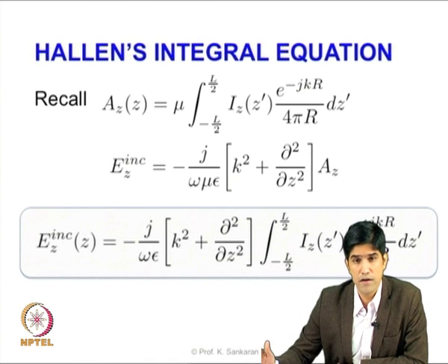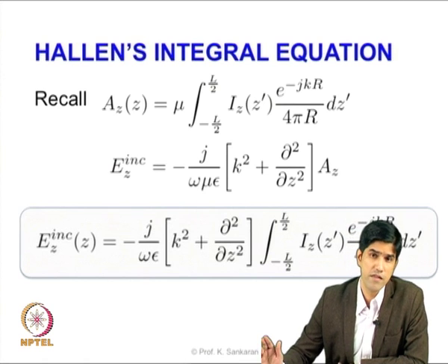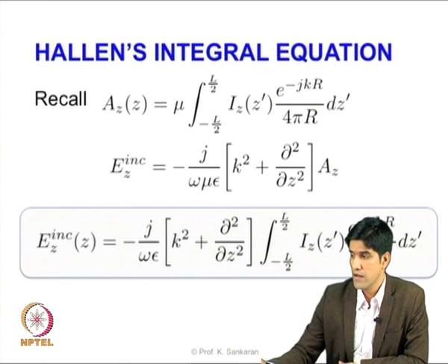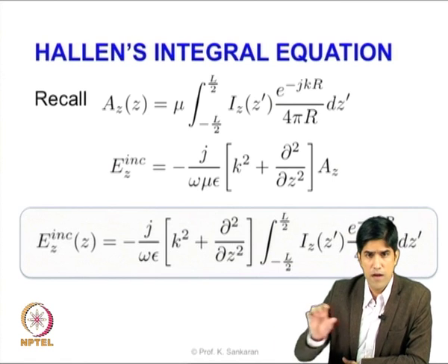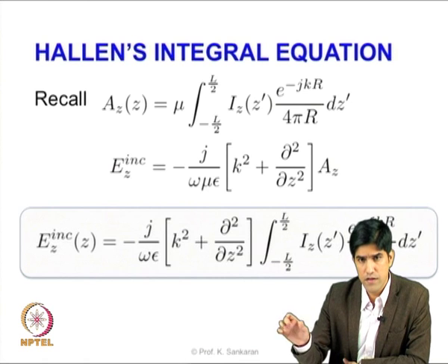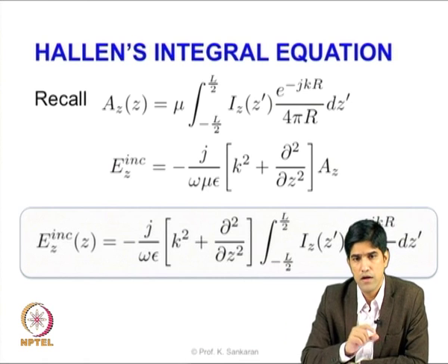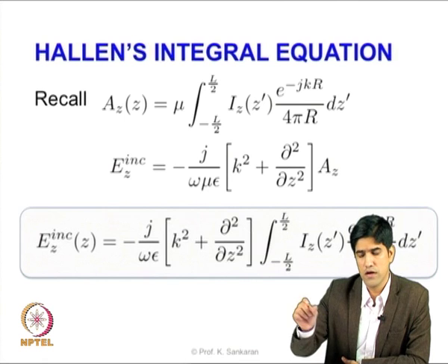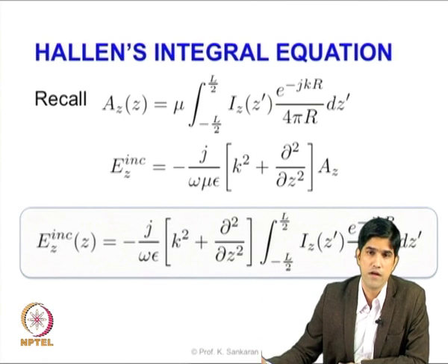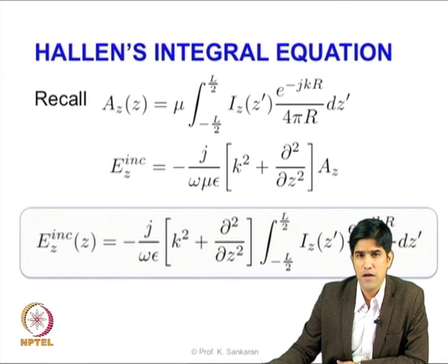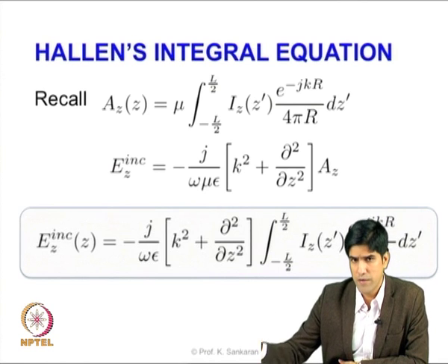So it has certain errors that are going to come because of this approximation, but there is a reason for doing this. The reason is that the convergence is going to be fast. As the number of elements along the line increases, the solution reaches the final solution quite a bit faster. That is what we mean by convergence. While we do this, we have to do a little bit more mathematics.